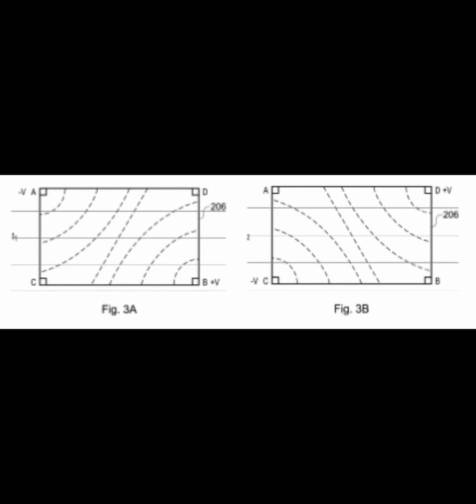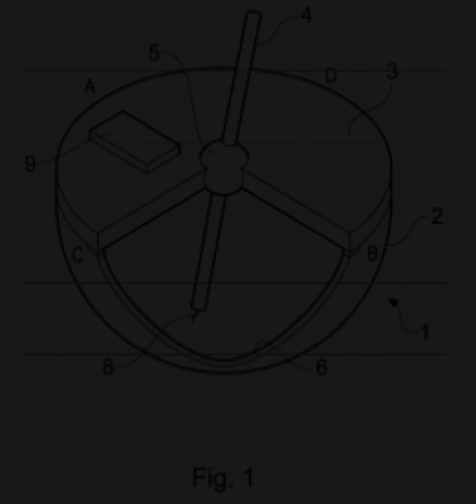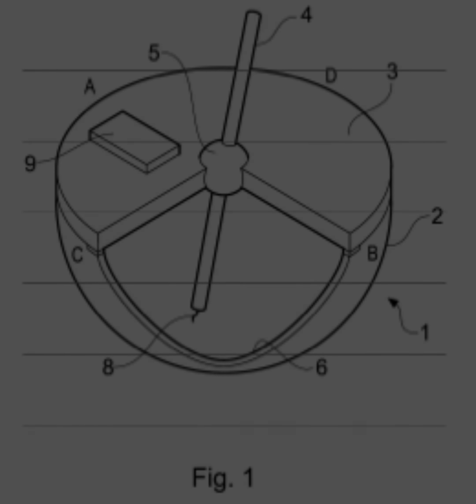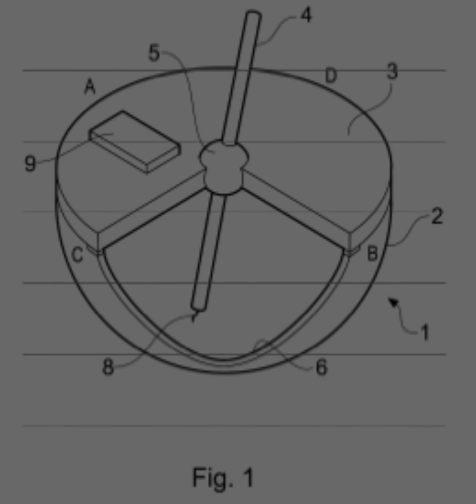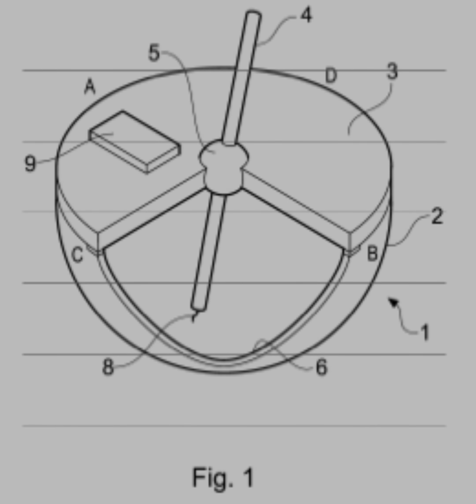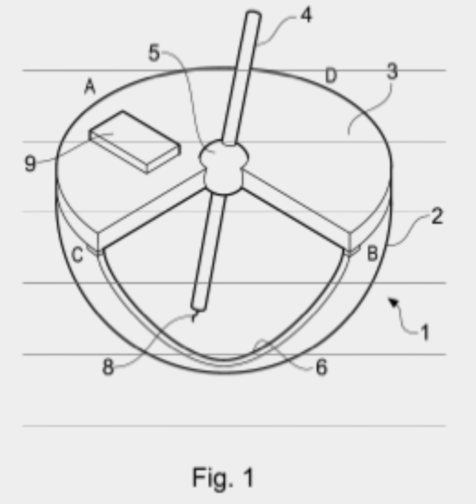Referring to figures 2, 3a, and 3b, the determination of the position of the actuator 4 will now be explained as follows. Let us consider that the actuator is not moving and that the conductive element is in contact with the resistive layer 6 at a point P. During the time period T1, the point P lies on the equipotential line V1, and the conductive element picks off the voltage V1. During the time period T2, the point P lies on the equipotential line V2, and the conductive element picks off the voltage V2.